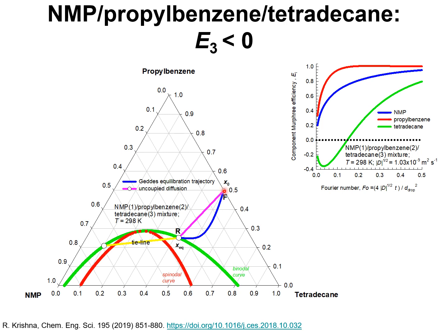We examine mass transfer in the raffinate phase as it moves up the column in the form of uniform droplets of liquid. Using the Geddes model for equilibration and the Maxwell-Stefan diffusion equations for this ternary mixture, we can calculate the equilibration trajectory the liquid droplets follow as they move up the tray in the liquid-liquid dispersion.